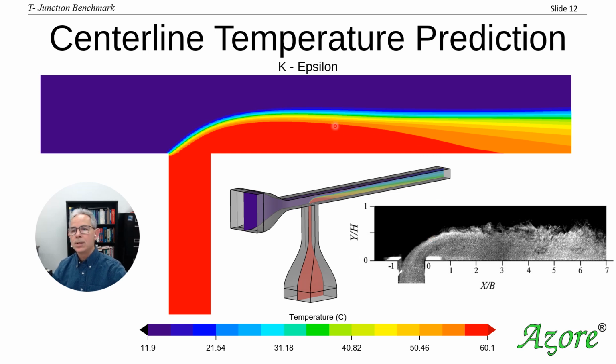But you'll notice that there's a very smooth transition between the cold and the hot as it progresses along here, and it's not very irregular shaped. That's because our turbulence model is doing a lot of averaging there, and that's the purpose of the turbulence model, to find an average value there. So we get an averaging effect. So we can see, if we remember, we looked at this dark spot down here, which represents how this cold gas was transported way down here, and that means that there is a cold area there.